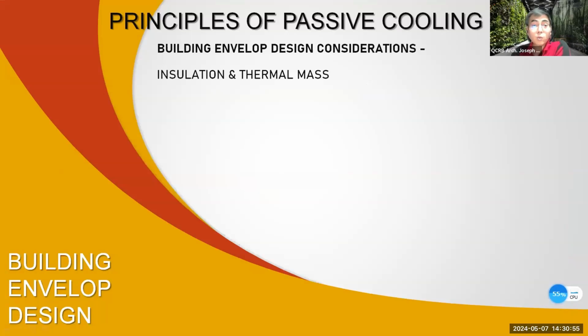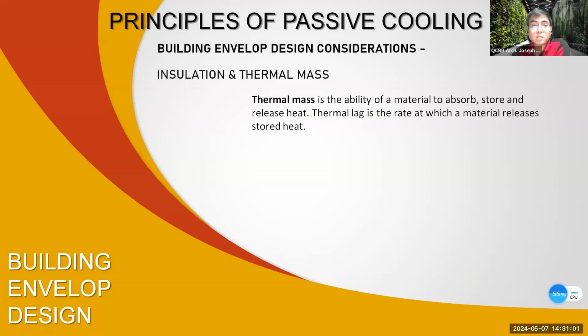So after learning about the building envelope, what we need to learn is the thermal mass. The thermal mass is the ability of a material to absorb, store, and release heat. Thermal lag is the rate at which the material releases stored heat. So ibig sabihin, the more mass you have, the more heat that you will be able to absorb.